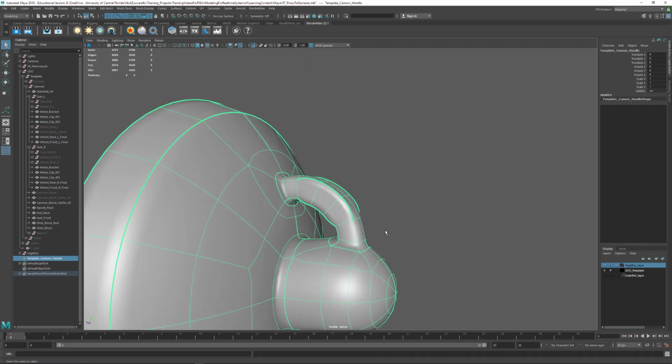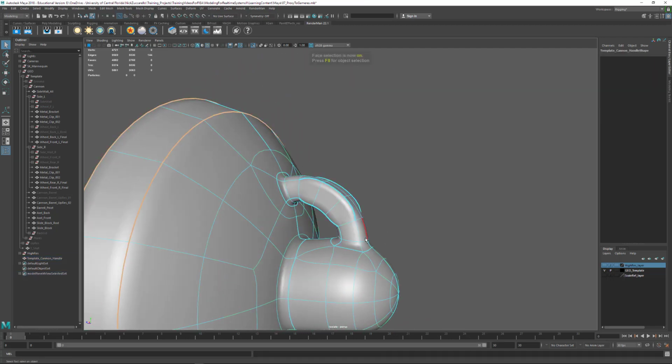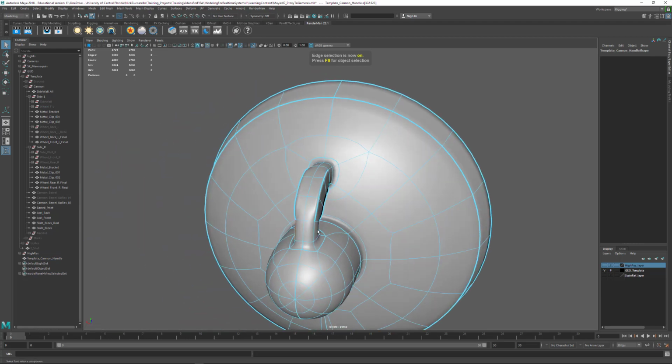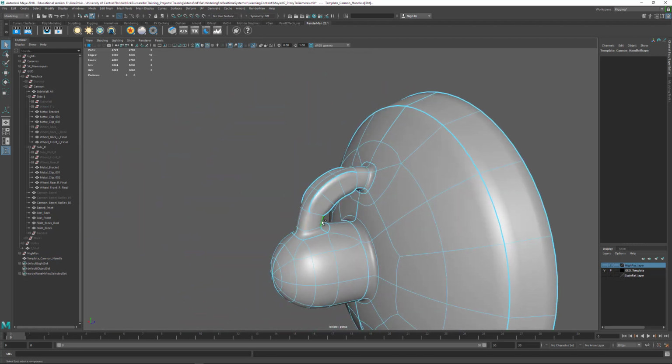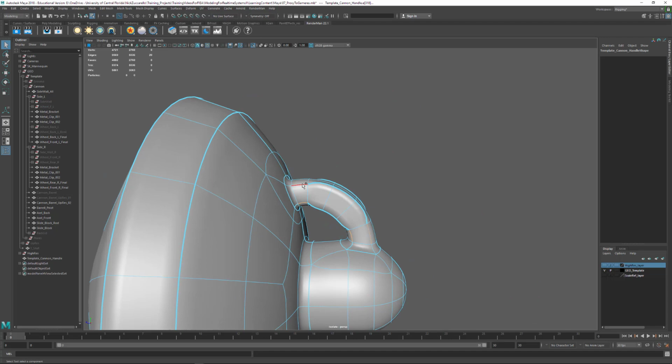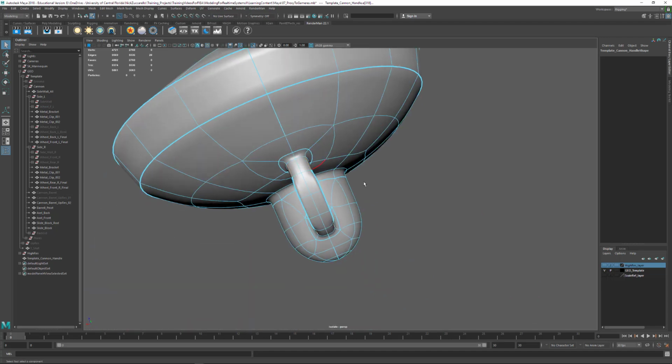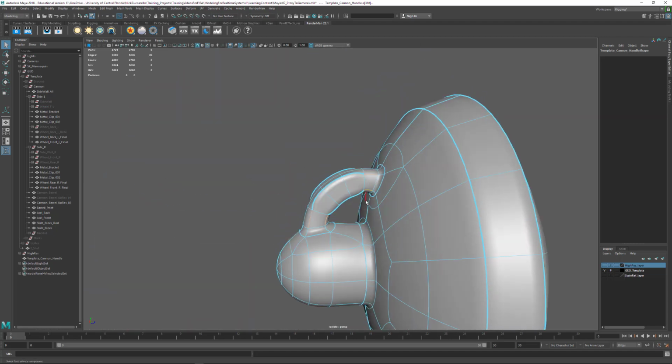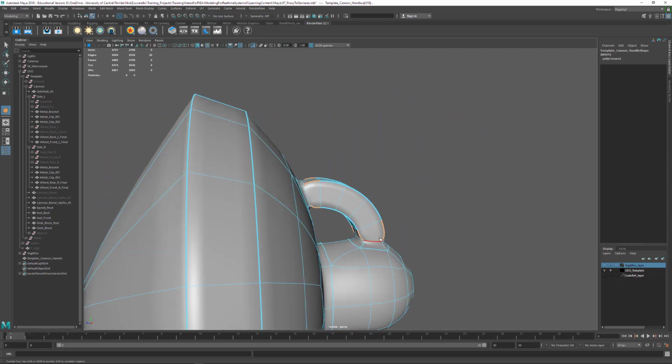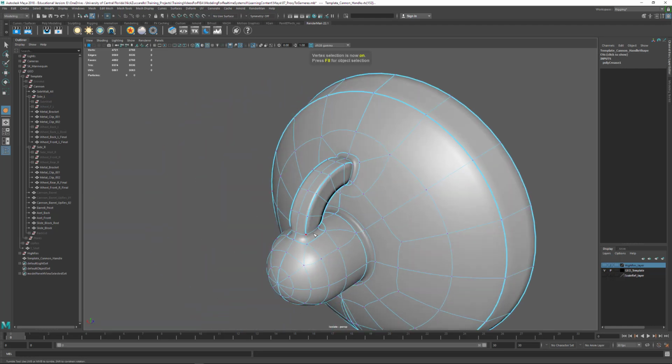Okay. Now, if we want to crease these, we can hit F10. It got rid of the creasing information that we had here and here, and here, and here, and here. So shift, right click, crease tool, middle mouse drag, just kind of like that. Now if we want this to kind of harden out, we can actually select verts, like this.